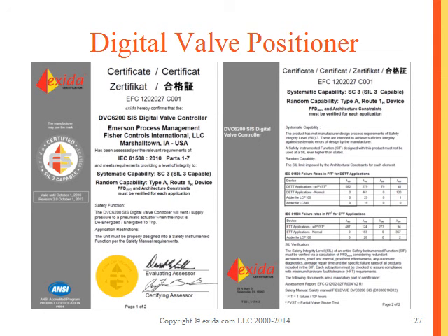There's an assumption stated there. And in this case, you see the digital valve positioner, and you say, well, I don't know what the actuator is. I don't know what the valve is. How can you put in a coverage factor? How can you claim that the failure rates are different for partial stroking? Well, the failure rates here are only valid for this product. So in this particular case, if you do a partial stroke test, certain functionality is exercised in this product, and you can detect certain failures. So some of the failures that were initially safe undetected or dangerous undetected now become safe detected or dangerous detected. But it only talks about the failure rates applicable to this product.